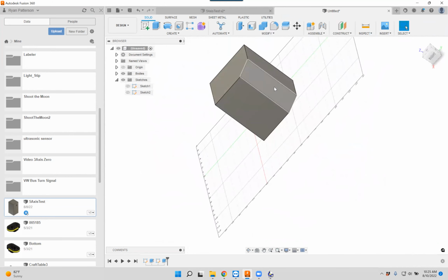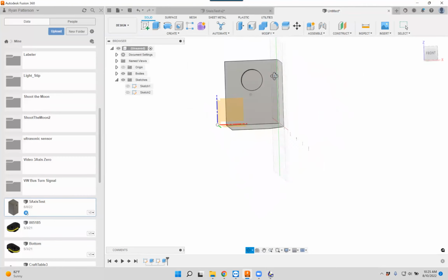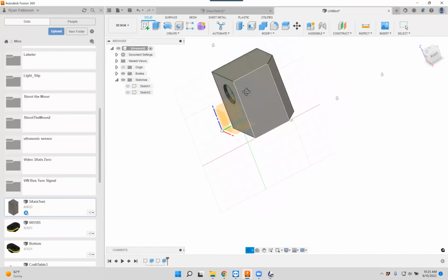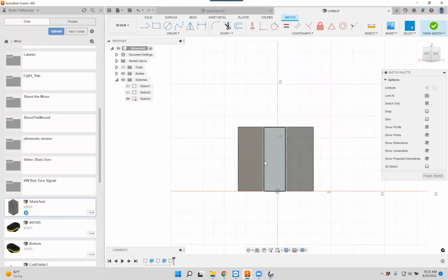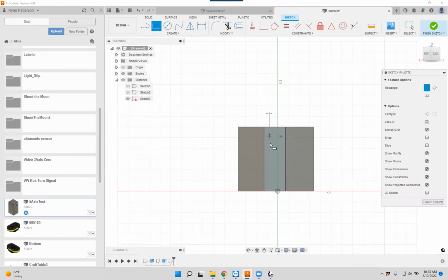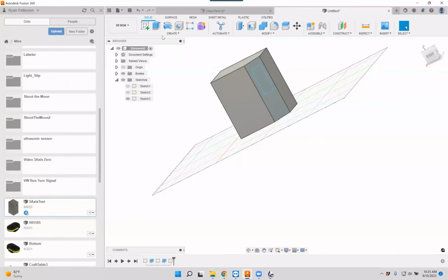And I'm going to create a sketch on this angle here by clicking create sketch. What face do I want, or what plane do I want to create this sketch on? Rotating the model around. It takes and views that, and we can see the little cube up here, how it's oriented. Again, we're in the 2D sketches. This time, let's just draw out a rectangle. Then finish this sketch.